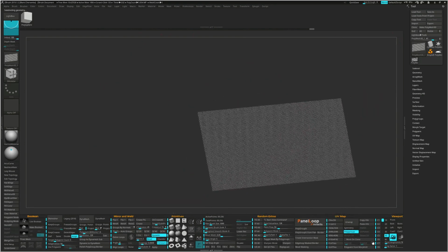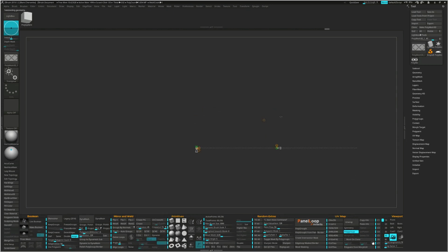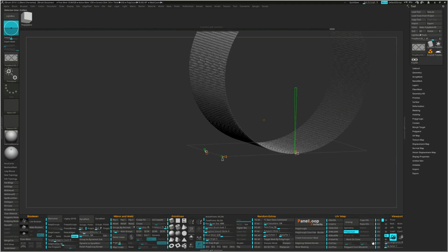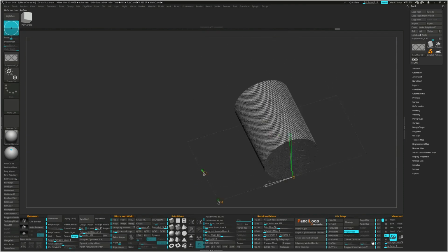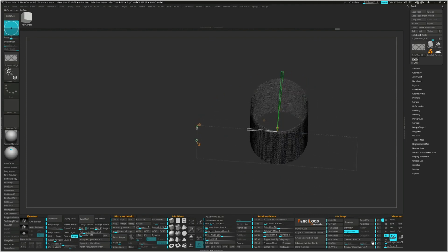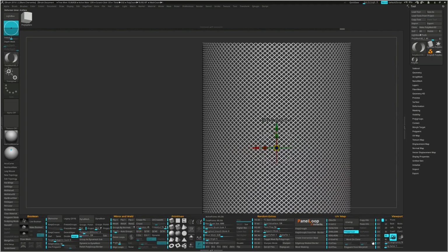Next is to make this plane a cylinder shape. Bring up the gizmo and click on Bend Arc. Go to the top view and move the cone until the angle is 180. The white cone will adjust the radius. Go back to the gear and press Accept.